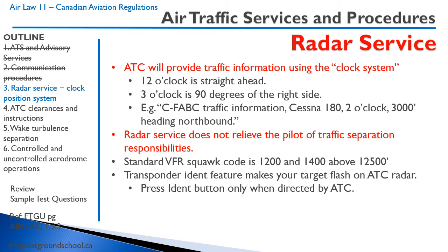Now, even though air traffic control might give you radar service and traffic service, it's imperative that you know this radar service does not relieve the pilot of traffic separation responsibilities when VFR. It's a big sky, they're small airplanes, and that's the principle of collision avoidance. You should be looking outside, making sure that you are not going to hit other traffic.